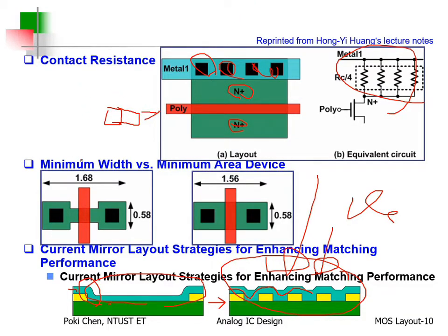And the other issue is, if you would like to get the transistor with smallest area, how can you do the layout? Many of the time, you may guess from the very beginning, I simply use the shortest length and the smallest width, okay? Will it generate the smallest area for your layout? No, usually not. Maybe in the past it is the case, but